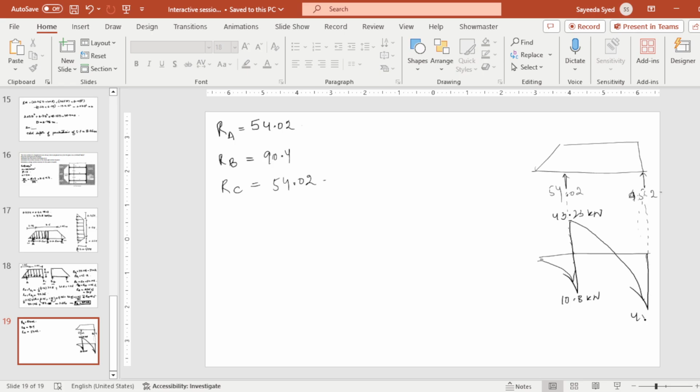So what was the second part of the question? Determine the strut loads. We did the envelope, we calculated the strut loads. Now the section modulus. Why we are doing this is because here we will know where shear force is changing its direction, the bending moment will be maximum. And if we calculate the x, we know the location of maximum bending moment.